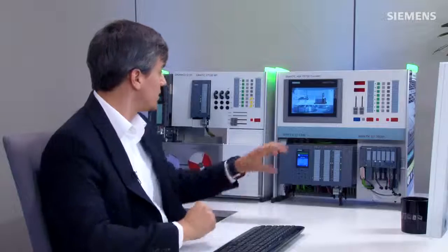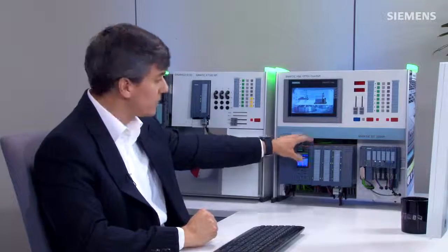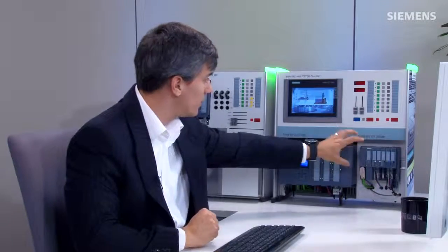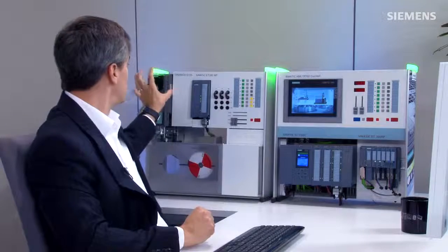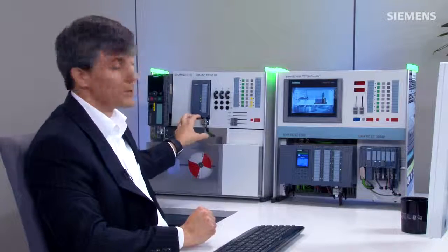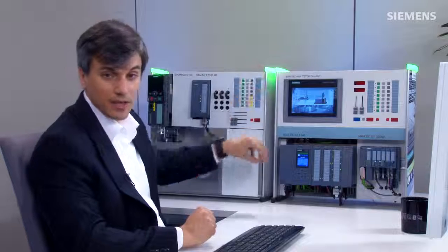Simple drive and motion control can be a huge benefit for any engineer because they can quickly and efficiently add standard drives and motion to the application, saving them valuable engineering time. Let me show you how easy they can be. As you can see, here is the S7-1500 controller, ET200 SP distributed I/O, a comfort panel, and here's the G120 drive and motor that we want to add over Profinet to this application.